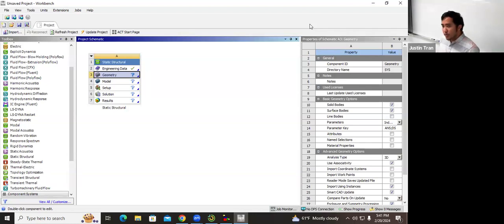So we're going to change one setting here. It's a setting that you normally don't change just because you run your analysis in 3D, but for this project, we have a 2D analysis. Under line 19, you can see that there is a setting for analysis type, and the default for this is 3D, just because for the most part, we do analysis in 3D. But just for this activity, I want you guys to change this analysis type to 2D.